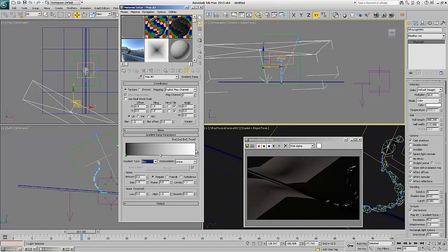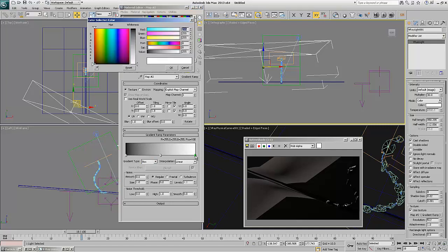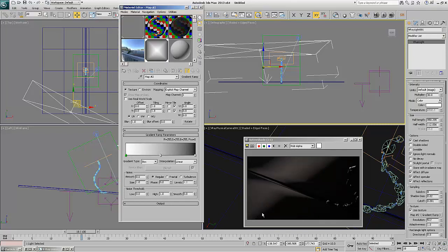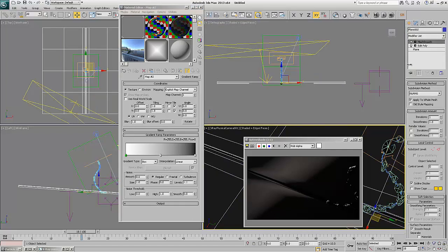It's in box mode to kind of hug the corners. You can see what it's doing to the reflection, but we want the opposite. So let's take this to black, and this to white, and you get this nice falloff on your lighting here. Now at the moment our hood is fairly low res. Let's really crank it up in the render. V-Ray RT works in the viewport, so if I want to see those iterations, I've got to turn it up here. And you can see we already get a much better look.